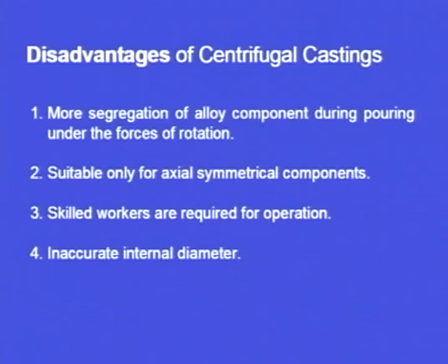So, we have to deal with this situation very carefully, and it is suitable only for axially symmetrical components. Of course, in centrifuging there may be a little exception from this point, but generally these casting processes are suitable only for axially symmetrical components, and skilled workers are required for the operation, and sometimes an inaccurate internal diameter arises.